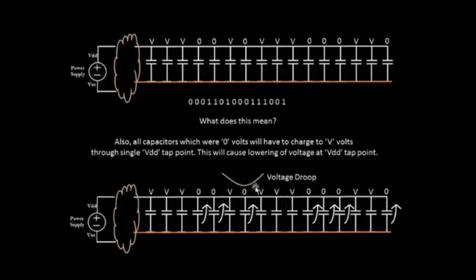And this voltage drop, as long as it is within the noise margin level, we are good enough. But if it goes into an undefined region, things become a bit unpredictable. So the phenomena that we saw were causing a lowering of the supply voltage. Either the VDD, which was supposed to be VDD on these lines, now goes somewhere less than VDD, and the VSS, which was supposed to be 0 volts over here, is at a somewhat higher voltage. So that's the problem that we see.